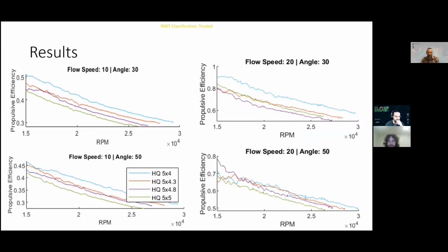So what we're seeing there is the highest pitch being observed at the highest advance ratio. So the initial conclusion is that none of these propellers are realistically being flown fast enough in this test case to reach their peak of efficiency. Everything that we're looking at is past that point as it decreases.